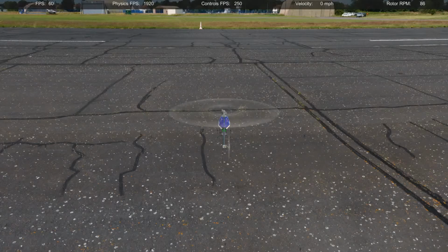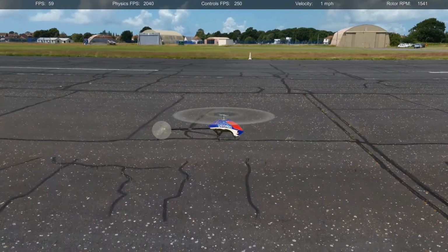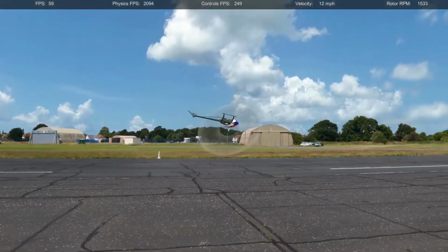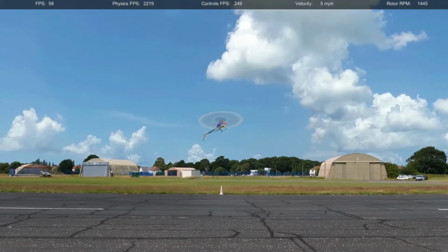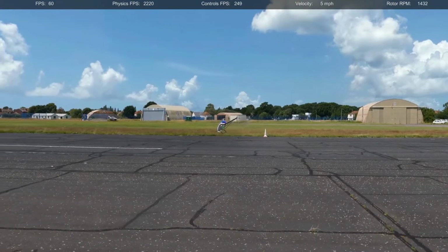Okay, the current approach, if you have a fixed wing where you can't change the wing, and if you're trying to cruise at different design points, then it really is perhaps more advantageous to go back to the old design and use the elliptical load. However, if we had camber changing flaps, we could change the design point and get that efficiency increase over a broad range.